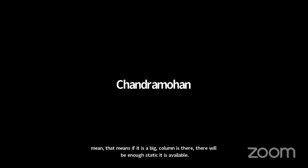If it is a positive suction pump, that means if there is a big column, enough static head will be available. So the elevation is not a problem. The only thing we have to check is the feasibility of approaching the valves and maintenance. Since we have enough head, we cannot install the pump at 2 meter elevation, because it will be hard for maintenance, for inspection of the pump or removal of the pump. So generally, if we have enough static head for the pump, the pump foundation height, from the ground level to the pump center line, will be hardly 300 to 400 mm only.